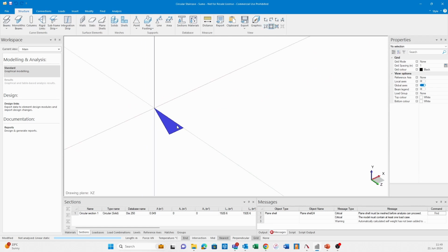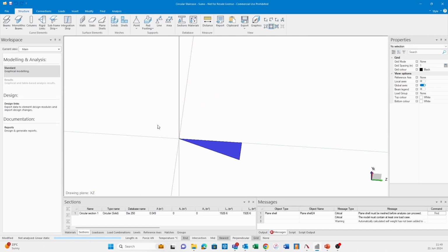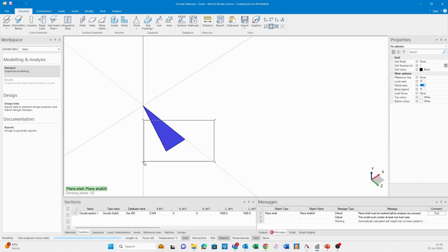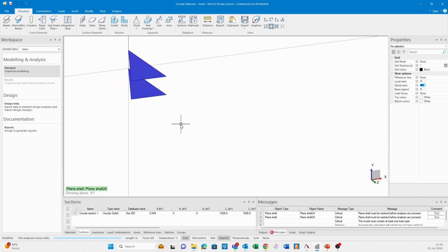All right. So now what we need to do is create our circular pattern basically. So I'm going to select the step, press copy. My step height is going to be 150. Snap to that point, turn grid snapping off, otherwise it's going to be terrible. But make sure that the nearest snapping is on. See, I snap to the column, tab, and change that to 0.15. Press enter and press enter again. And there's my first step.